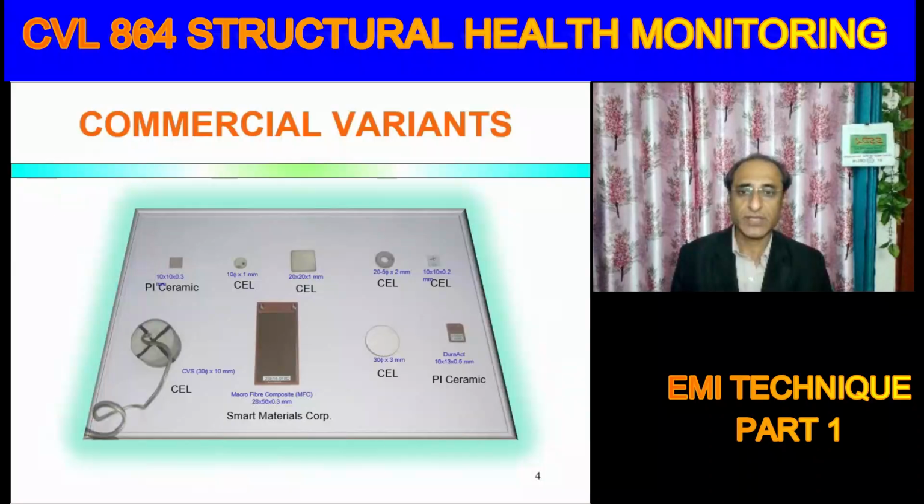These are some of the commercial variants. Here you see a number of different patches. For example, this is the one we have used in our lab. What you see here is a division in the form of an insulating boundary. The top electrode is there, and the bottom electrode is also wrapped around on the top surface. So when we bond the bottom electrode to the structure, at the top itself we are able to make all the connections or the soldering. But there are other types of patches.